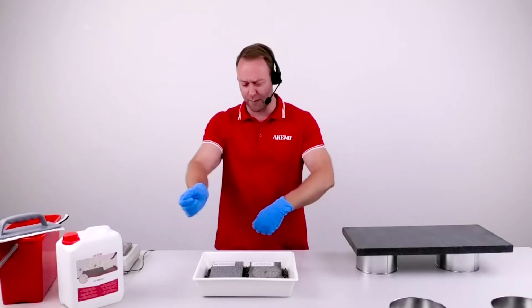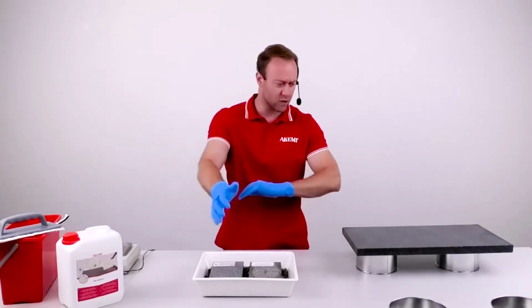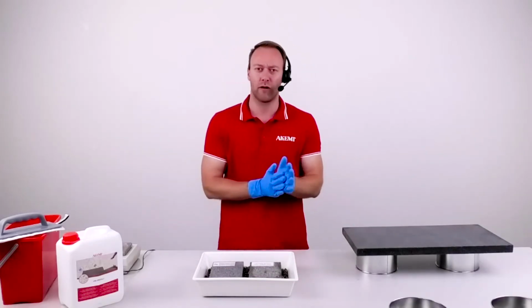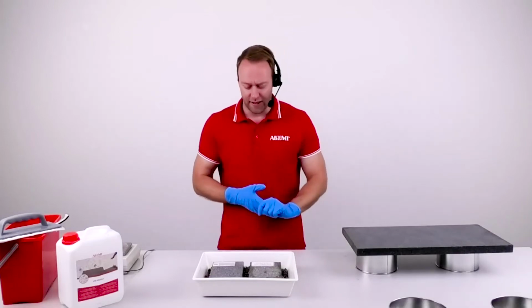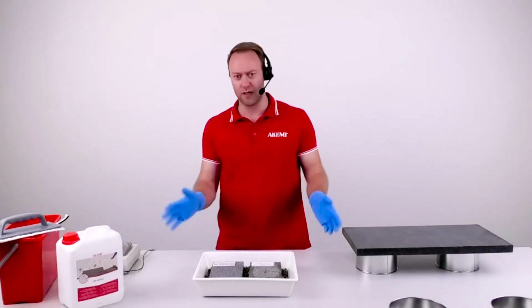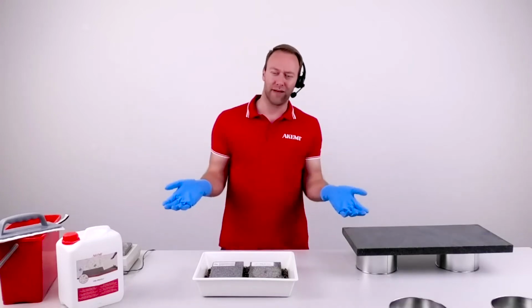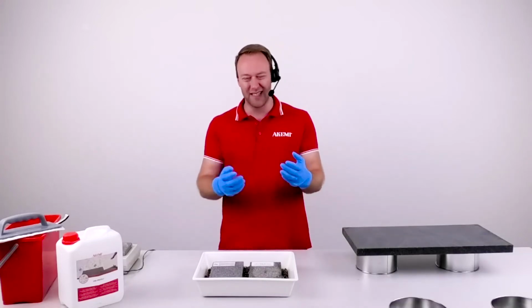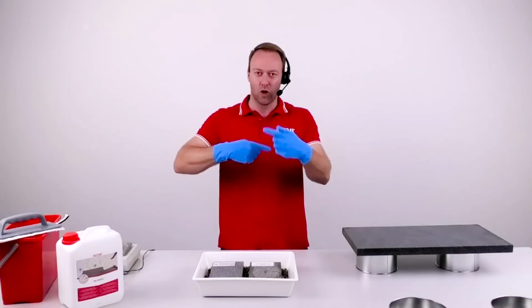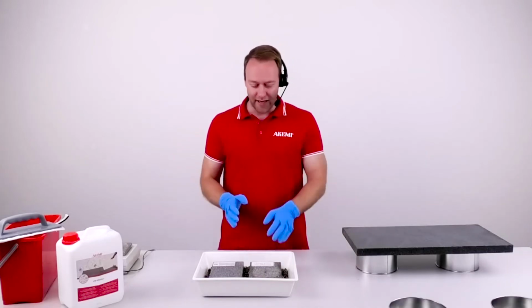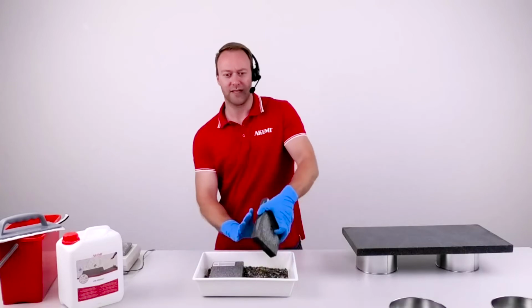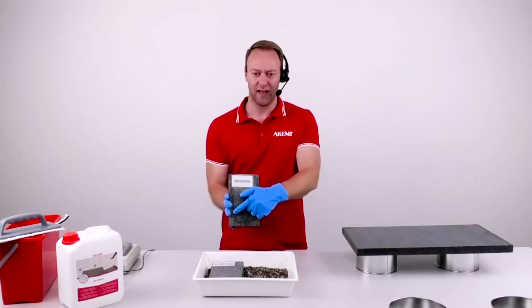Of course, I have some grout. I wash the surface to remove some concrete film, etc. And then there's a little bit of water. The stone is a little bit wet. It dries up, but then it comes back because the water is underneath. And if this process goes on and on for a few weeks, then these dark stains, like here, they get permanent.